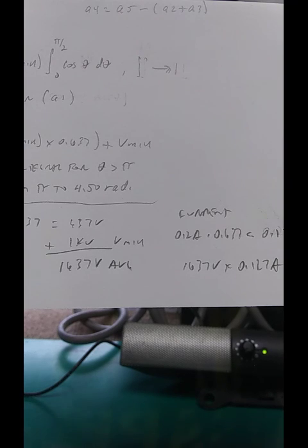The grid is the same. The grid's much easier because the voltages both swing the same direction as before. Just take the grid voltage swing and grid current off the graph, find the averages, multiply them together, and that comes out to be a shocking 0.7 of a watt for this drive case. So that brings questions as to whether that's legal under FCC, but if you're a qualified ham, you can figure that out.